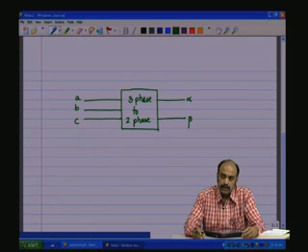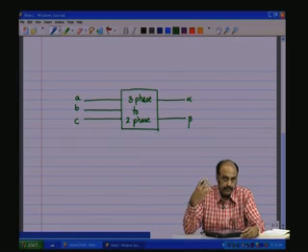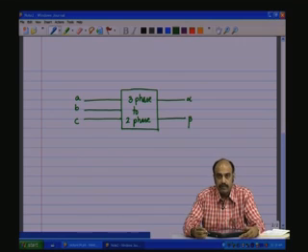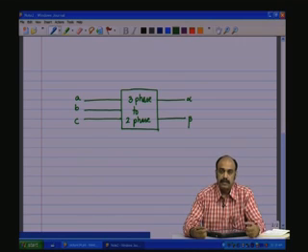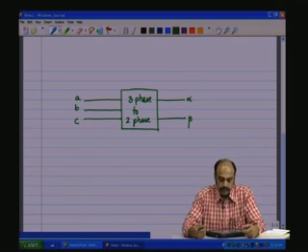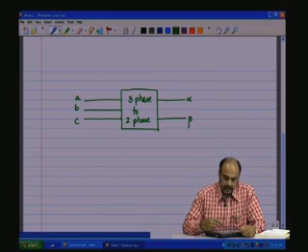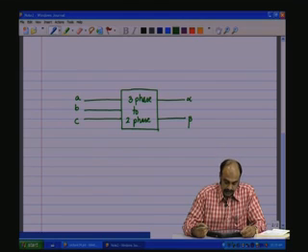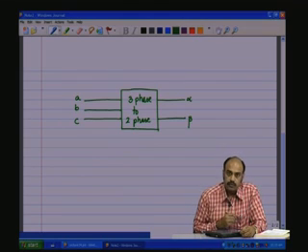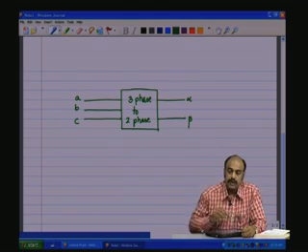A single phase motor can be designed such that you do not need that capacitor, because some of the single phase motors need the capacitor to produce a rotating field, which we will discuss much later. The 2 windings of the 2 phase transformer can be used for such an application of rotating a single phase motor. There may also be a few other applications where the 3 phase to 2 phase conversion can be used, and that